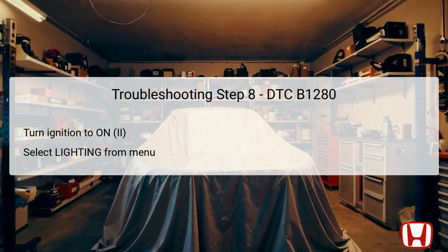Again, navigate to the lighting section of the Body Electrical System Select menu on the HDS. This step is crucial for checking the signal outputs in the system once more, now that the potential contributions of the combination switch have been removed. Such focused testing helps clarify whether the prior issues were switch-related or stemmed from other components.